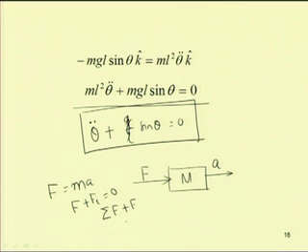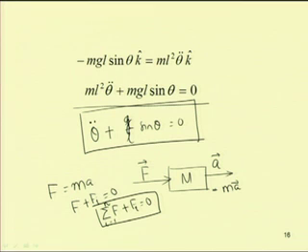If you have a multi degree of freedom system, you can write F plus F I equal to 0. That means we are converting a dynamical system to its equivalent static system by applying the D'Alembert principle. Here we are adding the inertia force, which is equal to mass into acceleration and acts in a direction opposite to the direction of acceleration. So, we convert the dynamical system to a static system.